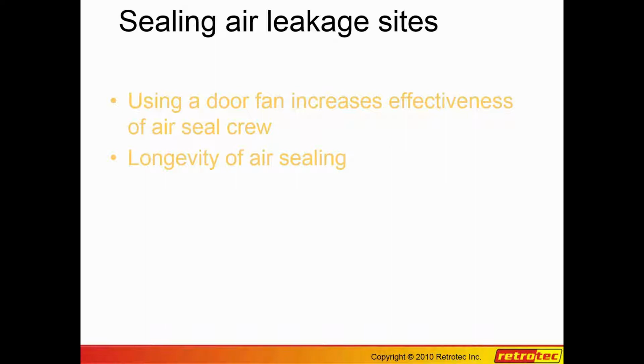You might find a leak, a crack that's 20 feet long, and you can see smoke going into it the entire length. You seal it and you remeasure and you see no difference. Or you might find, say, some kind of plumbing stack or something, you foam it, and the leakage might go down by 15–20%. This is really important information. Just because you put a lot of caulking material and so on, and you seal a lot of cracks that appear to be leaking, doesn't mean you've actually found the leaks.